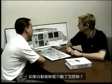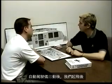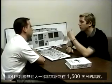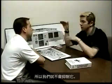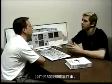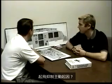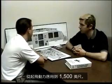How about if the autopilot kicks off? The autopilot kicking off is really a player for after we've taken off and I've engaged the autopilot. We don't want to inhibit it up to 1,500 feet like the rest of them are, so we just don't inhibit it. If I take off and start a turn and the autopilot kicks off, we still want to know about it. So that one is one of the strange ones that hangs out there. Takeoff inhibits are active from takeoff power application up to 1,500 feet.